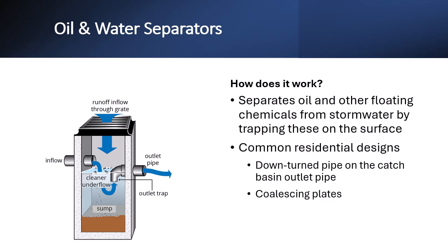Others may have coalescing plates, which are wavy edge metal sheets installed near the top of the catch basin. These plates help keep oil separate from the water at the surface so that it can be skimmed off. Though the use of these plates is rare in Spokane County, you will see an example of these on the next slide.